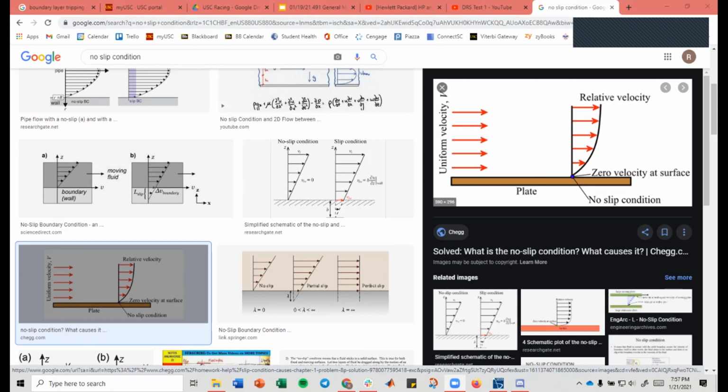If you're going down the highway at 60 miles an hour, there will be a point, the top of the boundary layer, where the air will be going the same speed as that free stream. So the distance between that height and your surface is our boundary layer thickness.